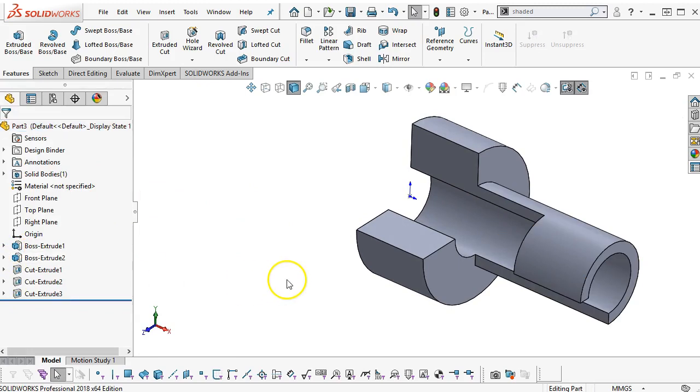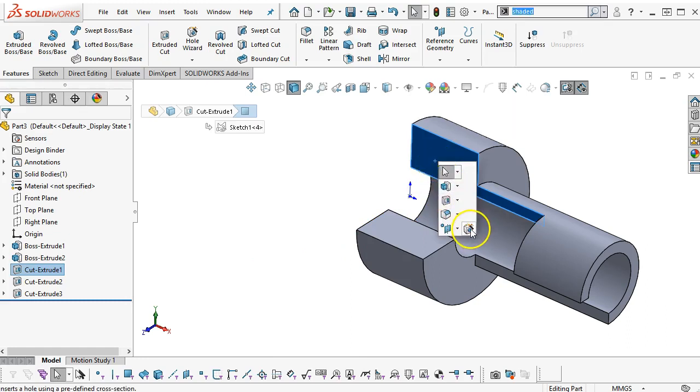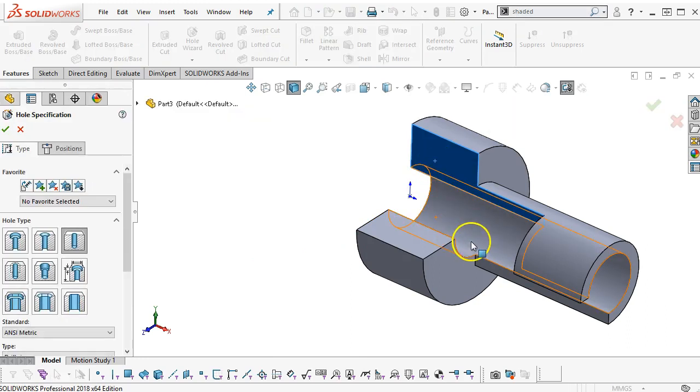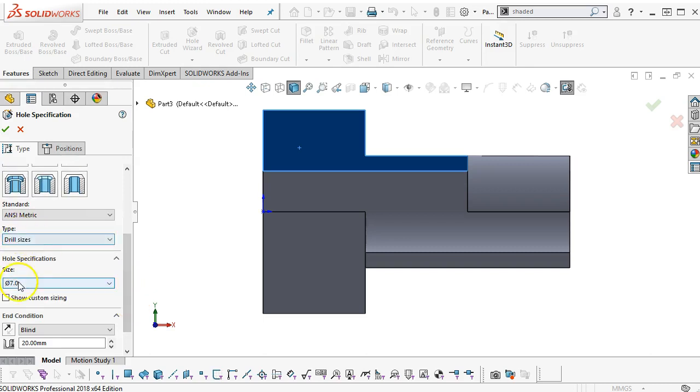Alright. So, again, I got good geometry, tried the contour and region. As far as the hole locations, we're going to go with the hole wizard, so S key, hole wizard. Go normal 2. This is a through hole. We have 5 millimeters in 2 places.